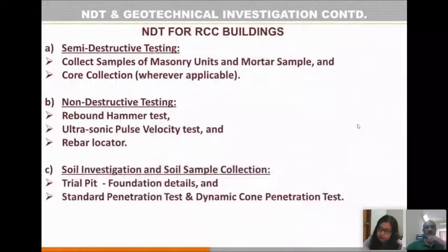In case of RCC buildings, you need to do the non-destructive test. For that purpose, there are different tests. The rebound hammer test is a very qualitative one, whereas the concrete core cutting is quantitative and more reliable, and that result can be incorporated in the model.